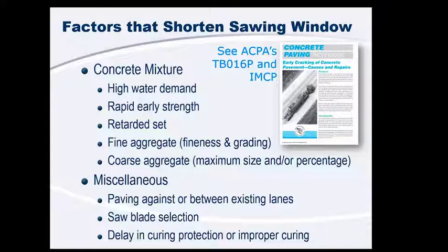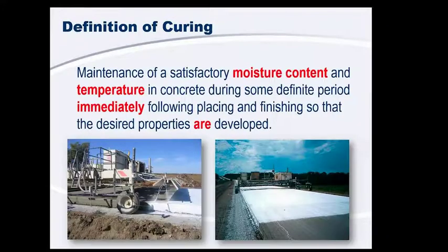Saw blade selection plays a big part in this as well. If you have early entry saws, you can obviously get on there and saw that joint earlier. We'll talk about that a little bit more in a few minutes. And curing. Curing is another big thing that has a huge impact on our sawing window, and